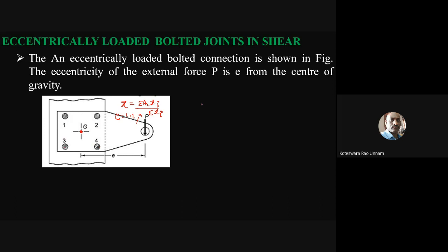In that case, what happens here is, so this sigma ai will become now n number of... okay, here it is, the formula is wrong. Sorry, here sigma ai xi divided by sigma ai, that is the formula for x bar. So if I take the diameter as the same, for each bolt the area is going to be only a. So your a1 is a, a2, a3 is also equal to a, and a4 is also equal to a. That means the area of each bolt is the same. All the bolts have the same cross-sectional area.